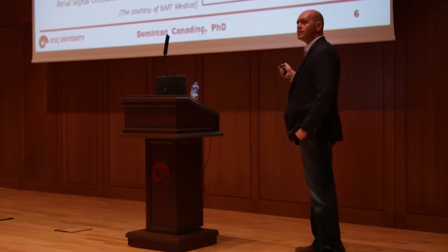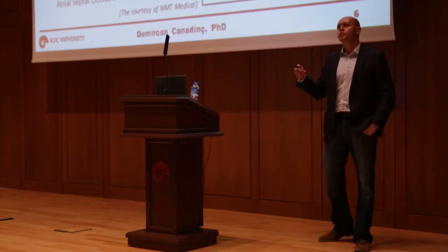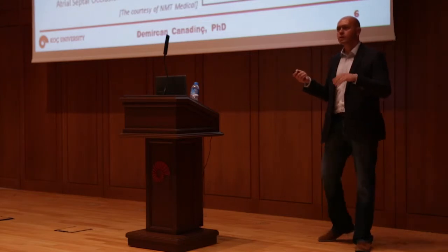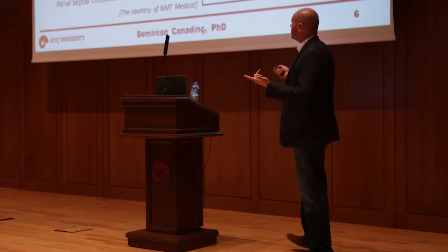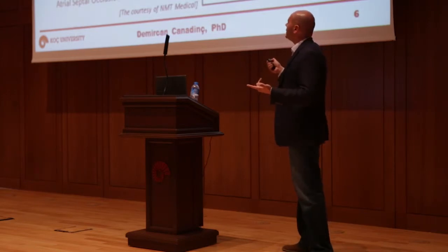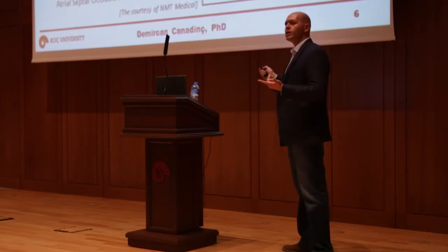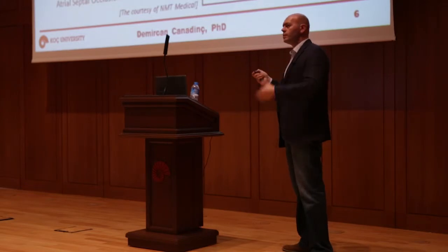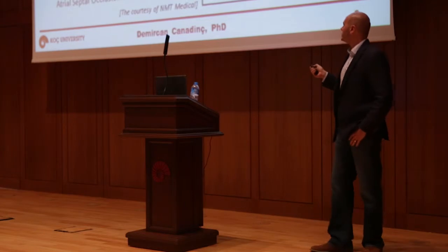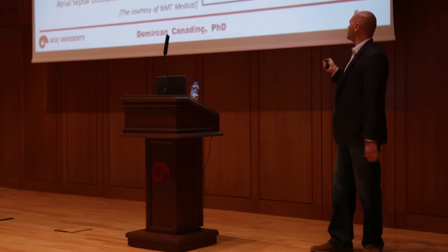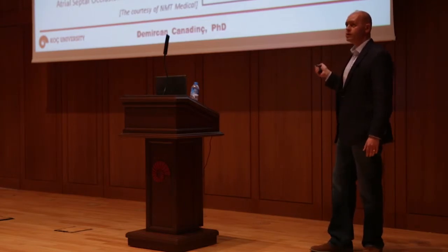and put it in its needle form, such that when the material is inserted into the body at room temperature, which is about 22 degrees C, and comes into equilibrium with the body temperature, which is about 37 degrees C, it assumes its high temperature shape, and then it opens up and it remains in place. And the same principle is what the famous self-expanding stents make use of.